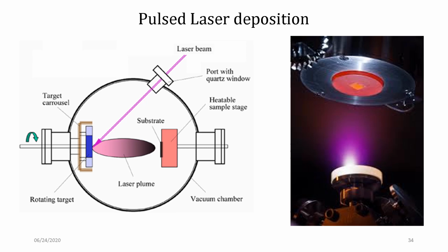There's support for that. Once a laser beam of very high power and very high repetition rate, which means you're sending extremely short pulses, hits the target, it can physically knock off atoms because of the local heating of the laser beam, and that forms a plume. This is called a plume, and it comes and hits your substrate. This plume has the atoms of the target material, which come and get deposited on top of the substrate, thereby allowing you to form very highly directional, highly oriented thin films.